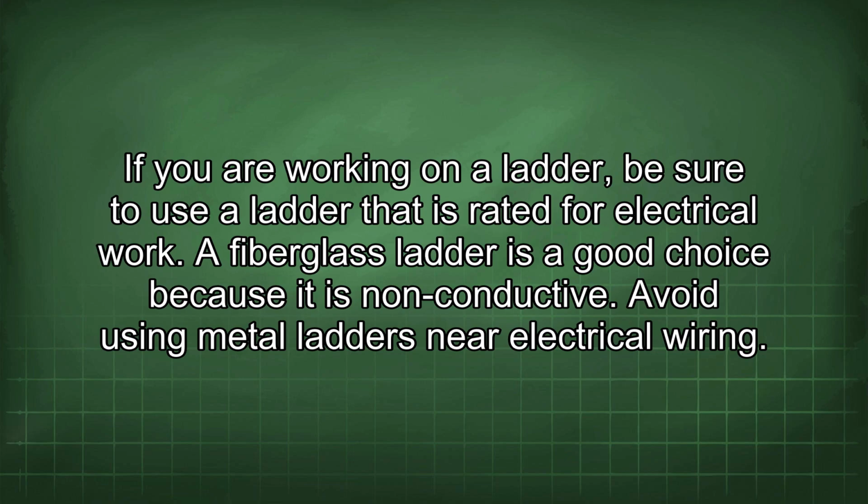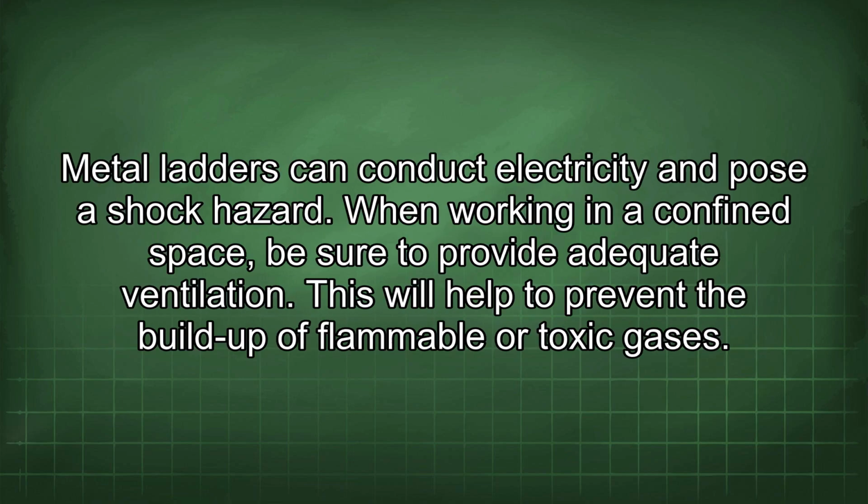If you are working on a ladder, be sure to use a ladder that is rated for electrical work. A fiberglass ladder is a good choice because it is non-conductive. Avoid using metal ladders near electrical wiring. Metal ladders can conduct electricity and pose a shock hazard.